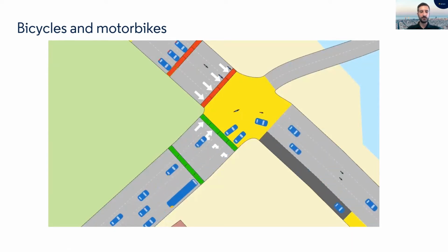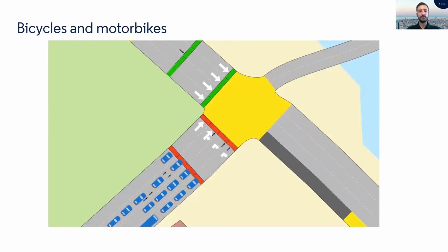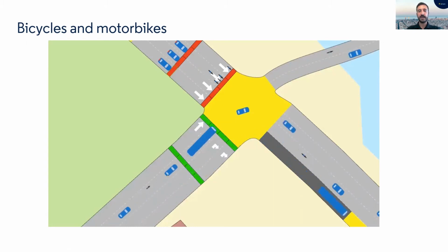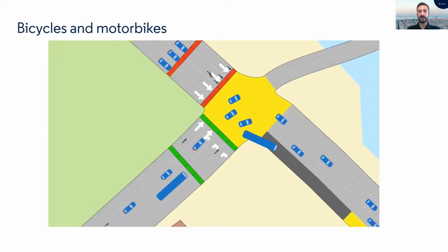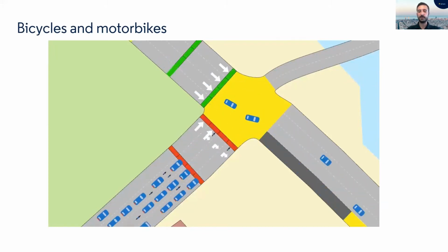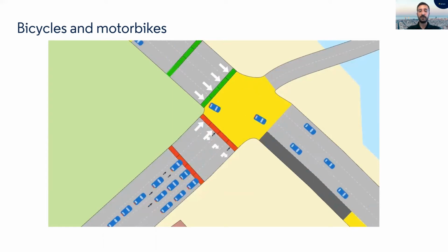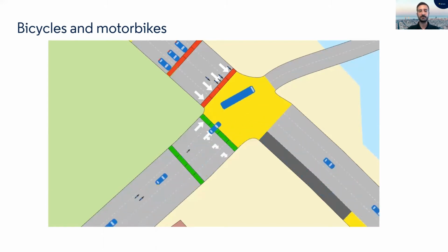How to activate this feature in Aimsun Next 20? It can be activated by vehicle type, either for the four-wheel or the two-wheel vehicle types, and/or by section object. For example, it can be activated only for motorbikes to reflect travel behavior, as it is in most of the European cities, whereas the activation of the model for all the vehicle types could be more suitable for Eastern countries where lane discipline does not exist.